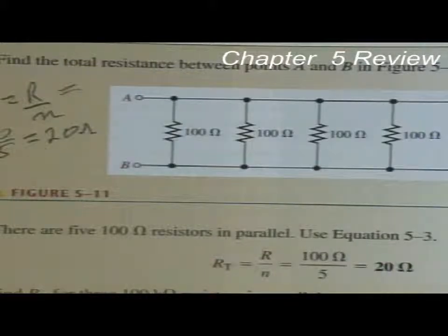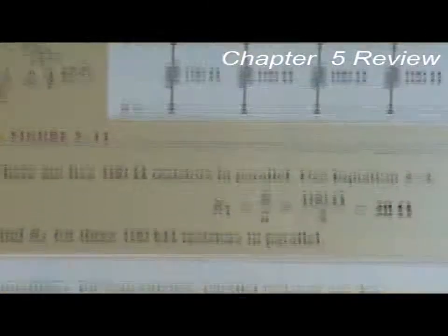So what I would suggest to you is, even when you have resistors that are easy to work in your problems, that you don't use that. What you do, you use what? The reciprocal formula and your calculator. Because you will always get the correct answer using the reciprocal formula. Now, let's go on a little bit.